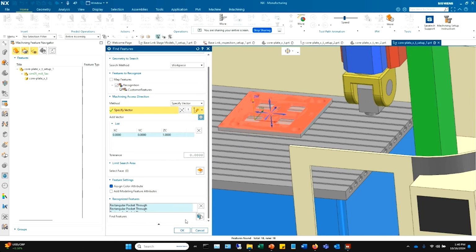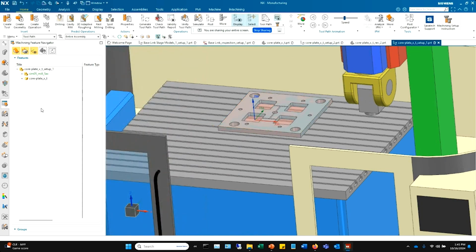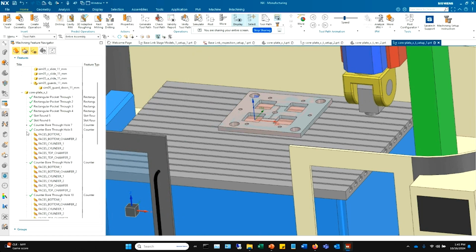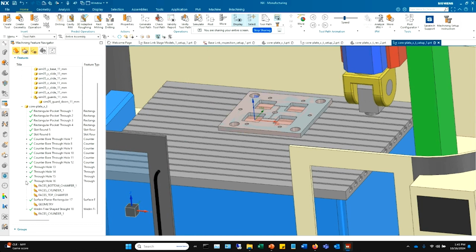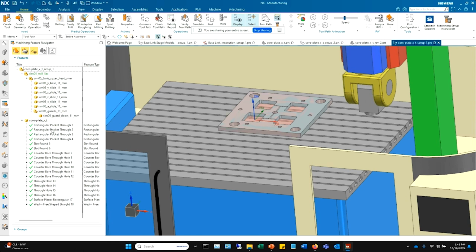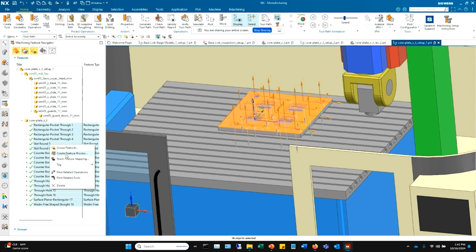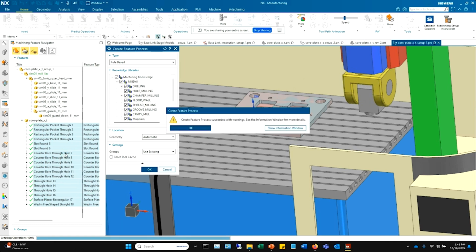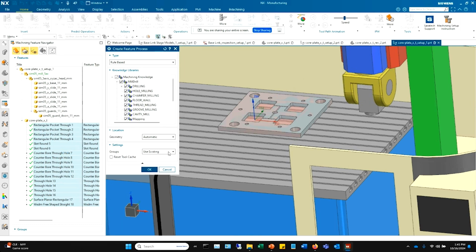The difference being the last program was programmed much like many of you program now, where there's no analytics behind it. Is this toolpath capable of making these motions within the machine tool? So now, this time when I generate, it's taking all of them into consideration. There will not be any type of approach errors, exit errors, collisions, gouges. There won't be over travels. There won't be any type of machine tool characteristic issue, which many times, in a well-known software out there that most people do all of their G-code driven simulations in,